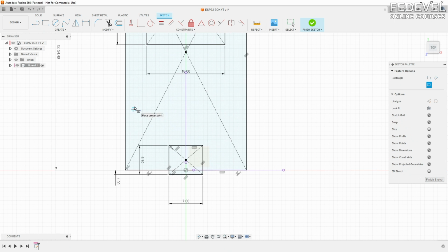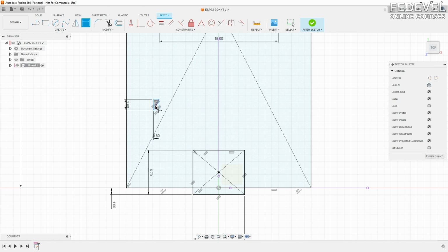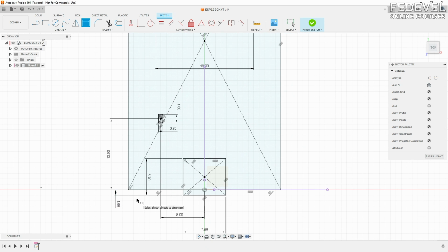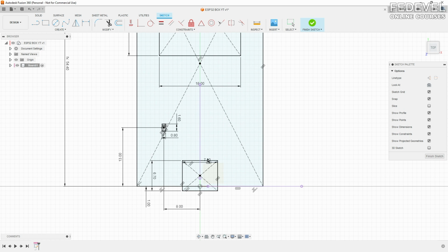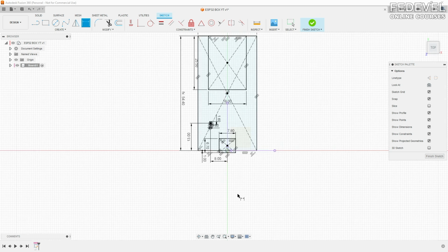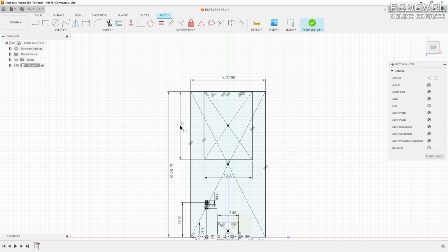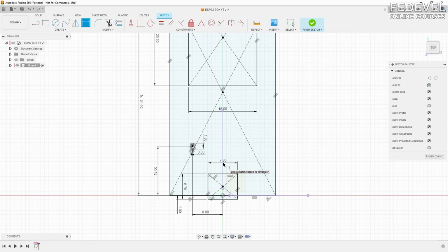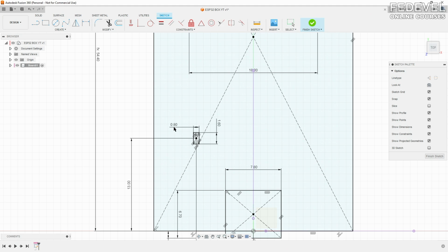Now the LED, it's somewhere here, and use 0.8 and 1.6. Okay, we would like to place it here, 8 millimeters, and here 13 millimeters. You can measure all these dimensions on a real board. I just make it a little bit nicer. If you move sketch like this, you can use this button to go to the default view. Almost done. Okay, this looks nice.